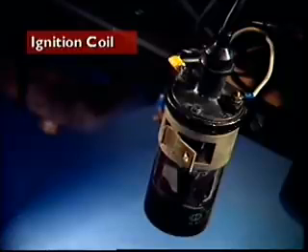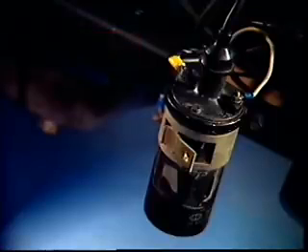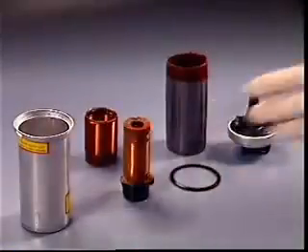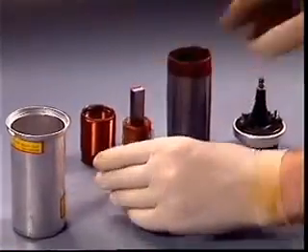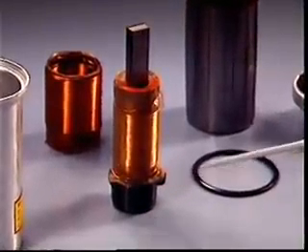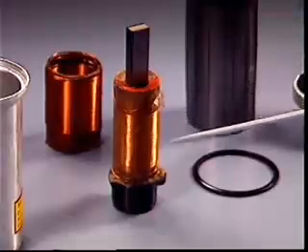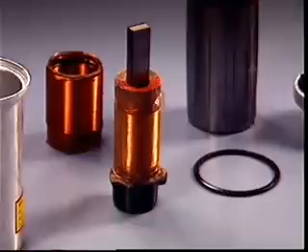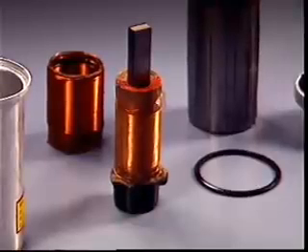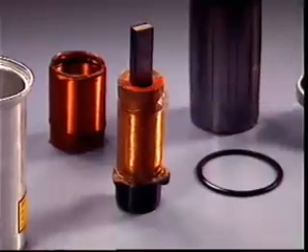The ignition coil is a step-up transformer which raises the nominal battery voltage of 12 volts up to the many thousands of volts necessary to provide a spark across the spark plug electrodes. A standard ignition coil has a rod-shaped laminated iron core, which is located centrally by an insulator at its base. The secondary winding, with 15,000 to 30,000 turns of very thin enameled copper wire, is wound around the core and is insulated from the core by layers of treated insulated paper.